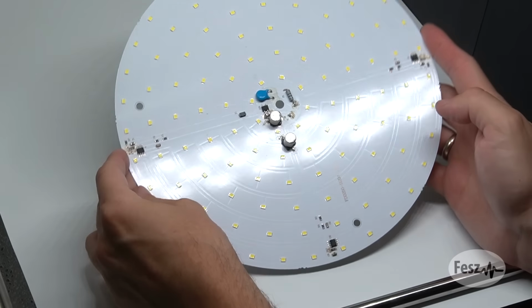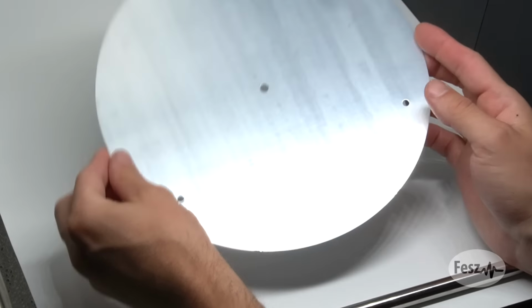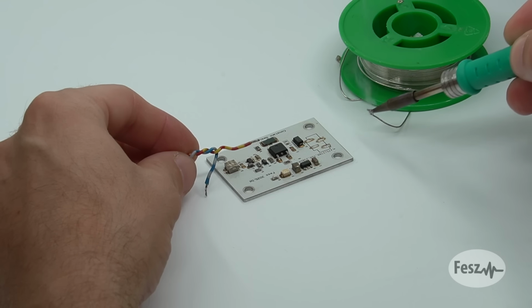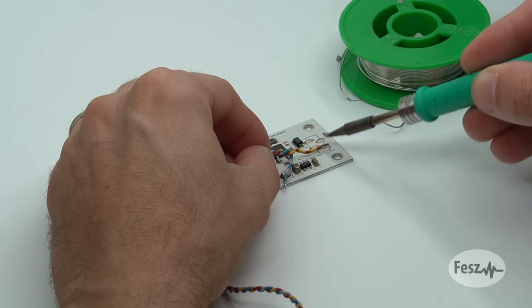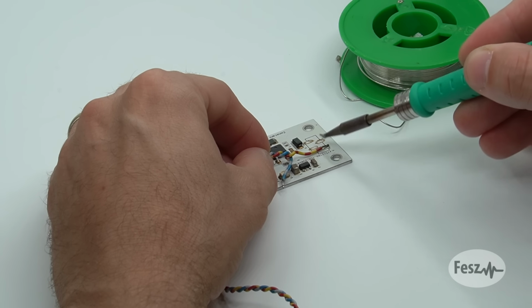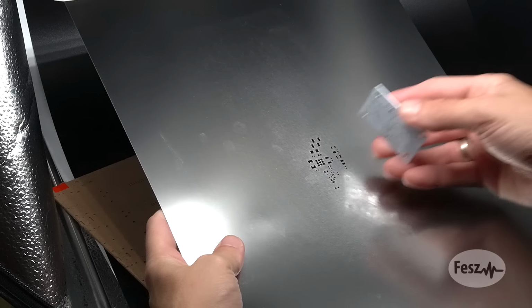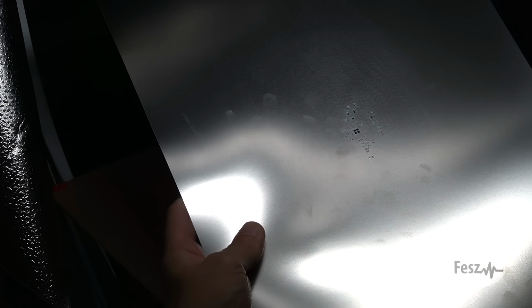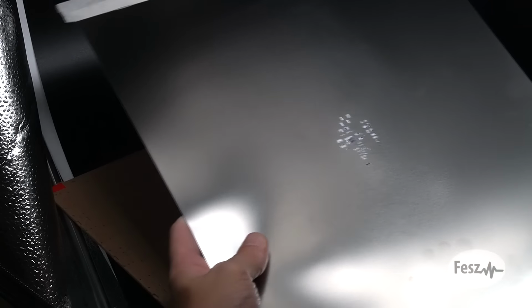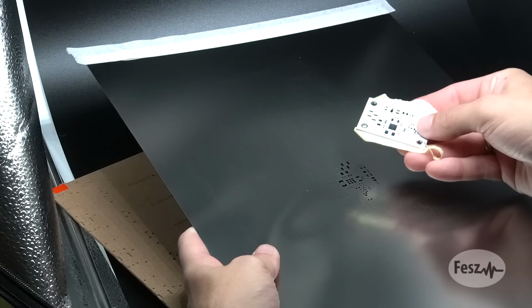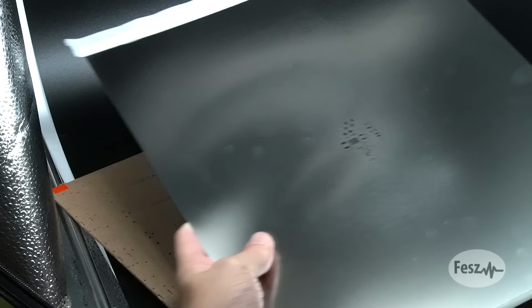Now, assembling aluminum substrate boards under industrial conditions is not an issue, but for the hobbyists, it can be quite difficult. The aluminum is highly heat conductive, so any soldering becomes very difficult. For this reason, I also got a stencil, and after a bit of struggling, I got the board aligned with the holes. To keep it in place, I did use some masking tape.